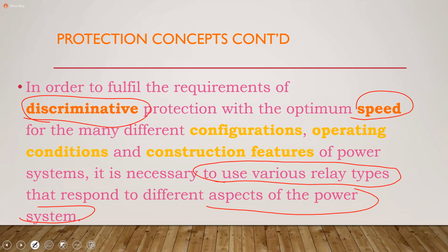So for example, remember earlier I mentioned that one of the issues that you may have in a power system may be a frequency issue. Now, do we have a frequency relay? Yes. Is it really measuring frequency? No. What it is really measuring is voltage. So we measure the voltage, and that gives us an indication of what's happening to the frequency.